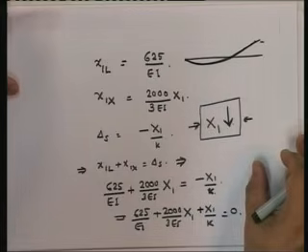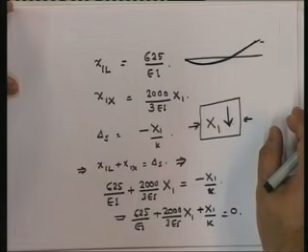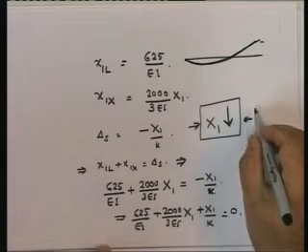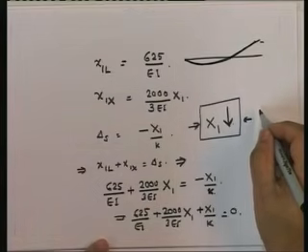Okay? So this is how you consider the effect of foundation flexibility. Note that in this particular case, as opposed to the truss, the foundation flexibility directly has an effect on the internal forces in the member. The bending moment diagram will change because the support reaction has changed.